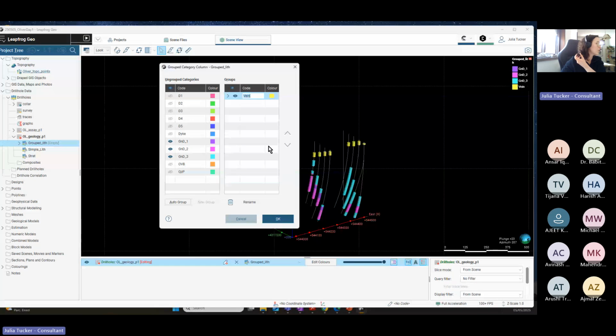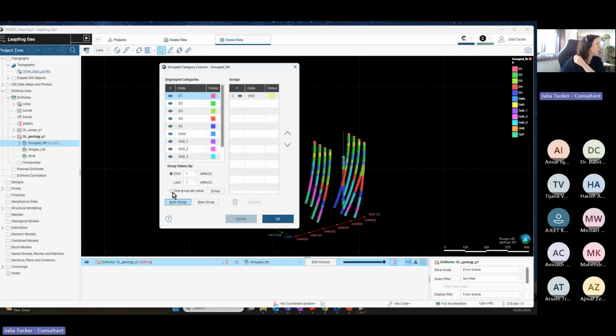And now we are just going to do a new group, and this new group is going to be called GND. So now that we have the GND as a new group, we can just take it out and build the new one by selecting everyone and auto group, one per value, new group. Oh, sorry, it's still not right.